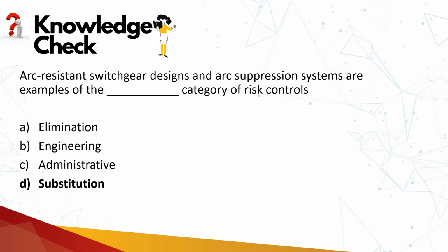It is again substitution, because we are substituting a metal clad switchgear with an arc resistant switchgear. So it is like I am substituting one type of hazard with another type of hazard. If I'm making some changes within my existing switchgear, that will fall under engineering control.